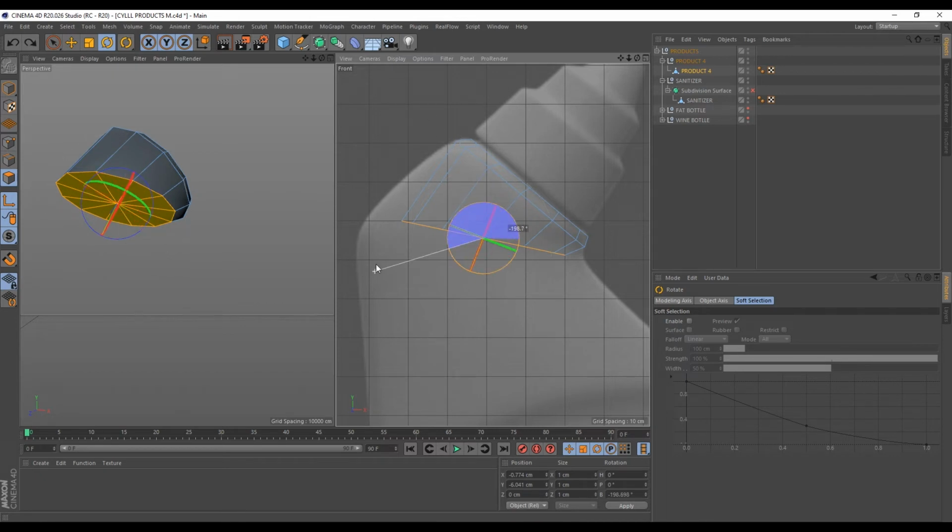So you see this is not affecting the object at all. This is just the gizmo. So I'll place the gizmo here this way. And if I switch back to my move tool, you see I have this aligned. So now I can hit T. Then I'll uncheck this axis mode. If you don't uncheck this axis mode, we can't continue shaping our object. So uncheck this axis mode here, and we can scale this on the x-axis alone.